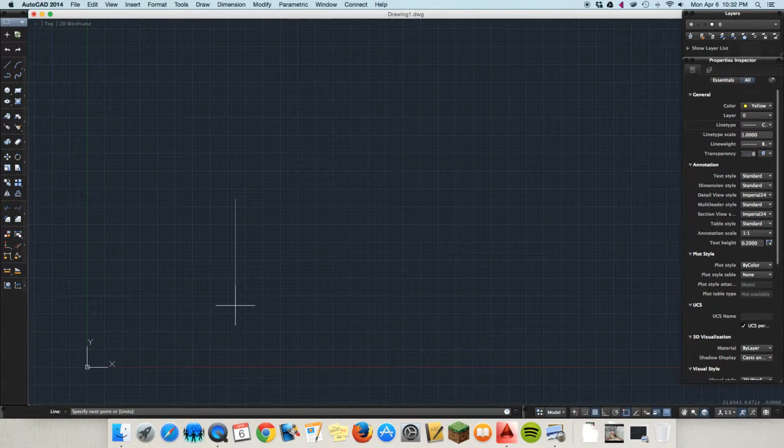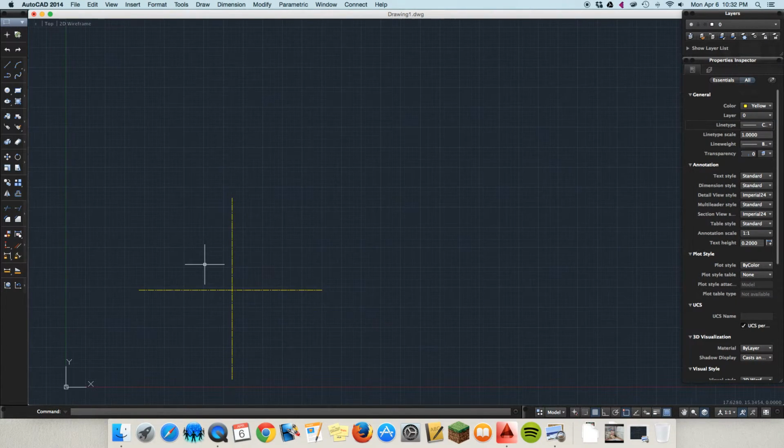I'm going to do the line that goes down. Now to force the line straight down, if I hold down the Shift key, it will create something called ortho mode in the program, which means something will be straight up and down or straight left to right. As you can see, I've done that. I'm going to do the line tool again, and again, this does not need to be centered. Let me click the line tool, sorry. Click one side, hold down Shift, and click the other side. So good. Now I'm going to zoom in so you can see kind of where we're at.